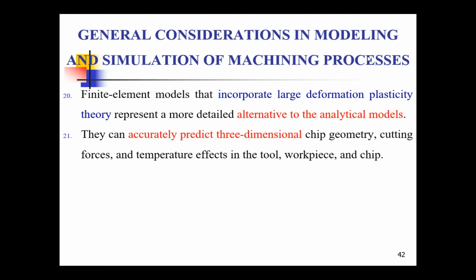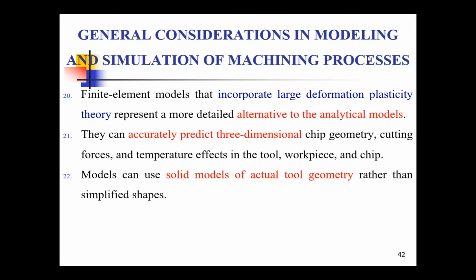So that we can clearly see the geometry of the chip, the chip morphology we call it, the cutting forces, the temperatures, changes in the tool, workpiece and chip, each and everything we can visualize by means of this plasticity theory. So the models use solid models of actual tool geometry rather than simplified shapes.